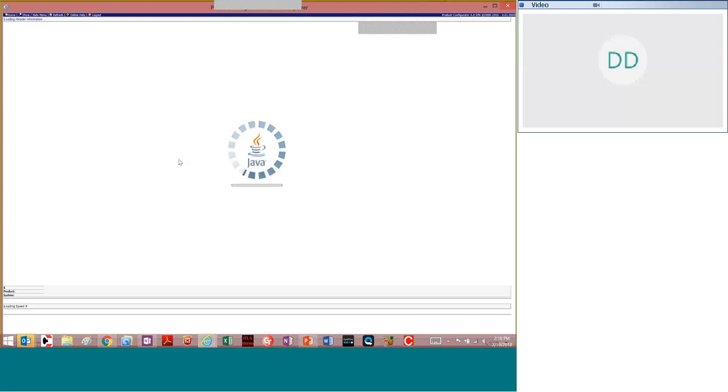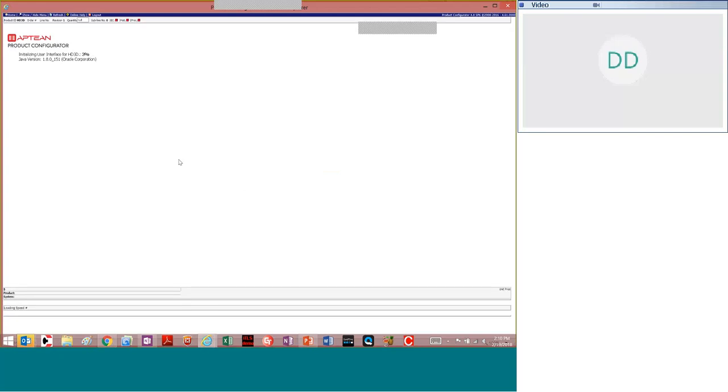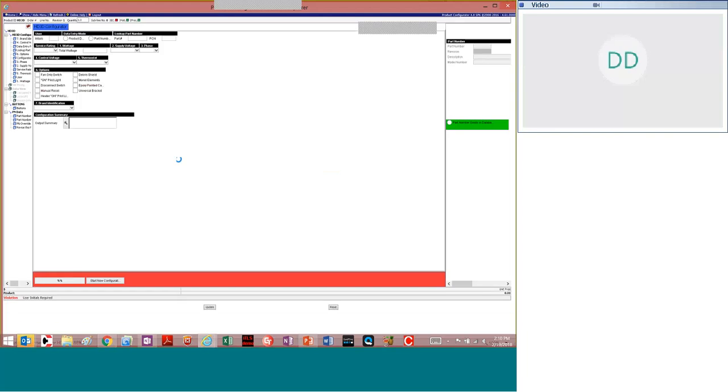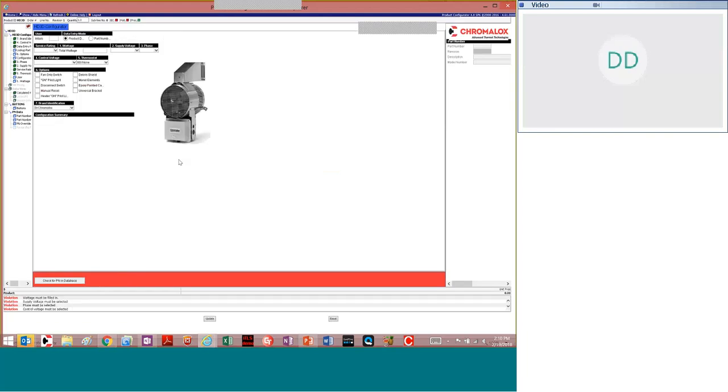Now, back to that small little chart I showed you, why are HT3Ds so important? As from the first presentation, these are your hose down units. They're stainless steel. NEMA 4 is moisture resistant, but NEMA 4X is corrosion resistant, hence the purpose of the fiberglass box and the stainless steel design. And this really is a product-leading design. Everyone else still has the junction boxes with the door facing down, and I can tell you that, as simple as that sounds, was a huge improvement on these designs.